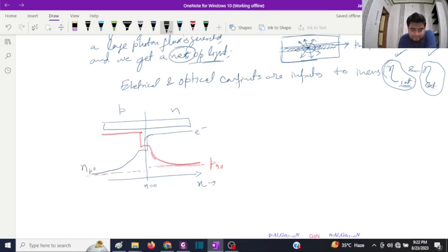That we all know from the diode equations. Now if you look at this junction region, with some little forward bias, a lot of electrons and holes are present. In the N region, we have a very high number of electrons, but holes are quite low. In the P region, holes are quite large, but electrons are small. For recombination, of course, it happens between one electron and one hole, right?